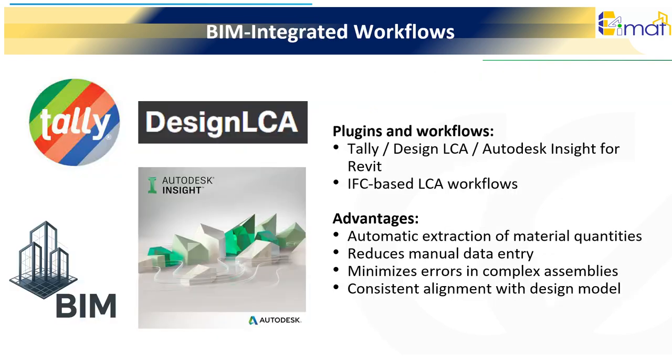The second group of tools are BIM integrated workflows, which connect the design model directly to the lifecycle assessment. Plugins and internal tools such as Tally, Graphisoft Design LCA, or Autodesk Insight can automatically extract material quantities straight from the BIM model. This greatly reduces manual data entry, which is one of the main sources of inconsistencies in traditional LCA workflows. These tools also minimize errors in complex assemblies, because the quantities come directly from the model geometry rather than from separate spreadsheets or manual takeoffs.